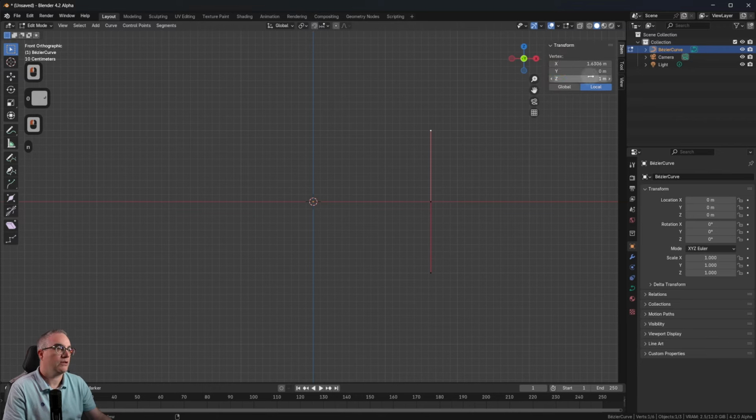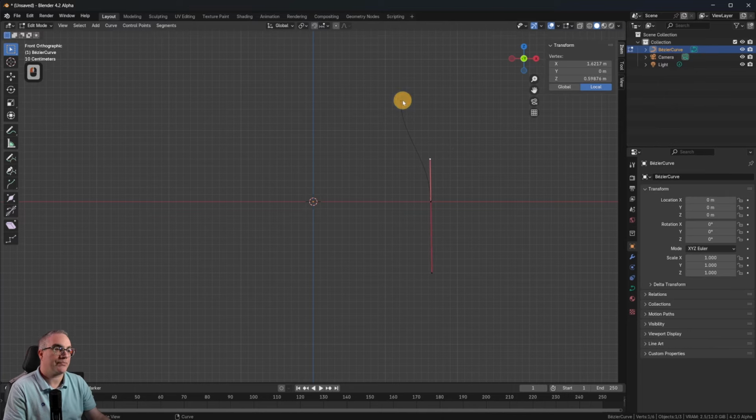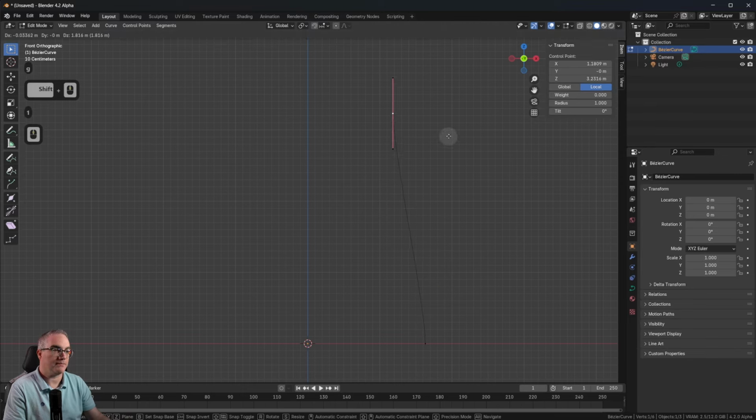So in here, when you have a vertex selected, you can specify the exact location of a vertex. Of course, you can always hit G to grab a point, or let's grab this vertex, move it around with G and use the mouse, or we can set the exact location here. So if I want this to be exactly on Z 0, I can do it in here. So this thing we want to be rotated straight up. So like this. And then here we're gonna model our bottle.